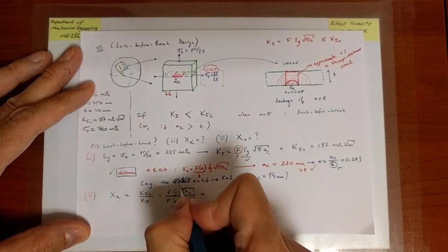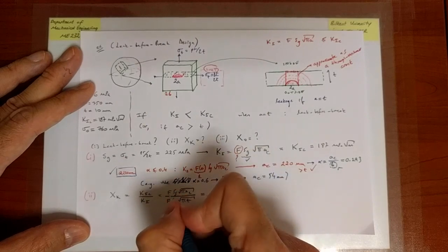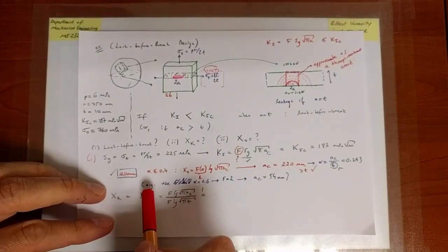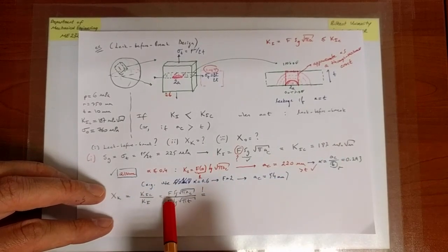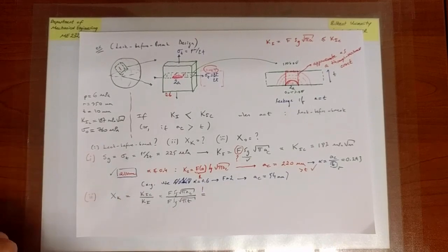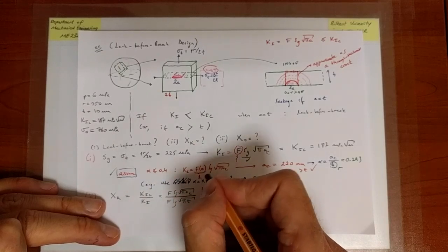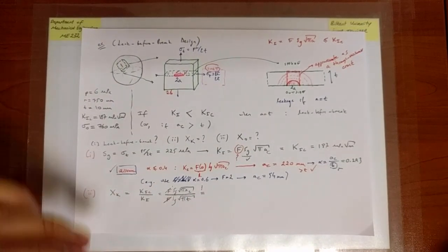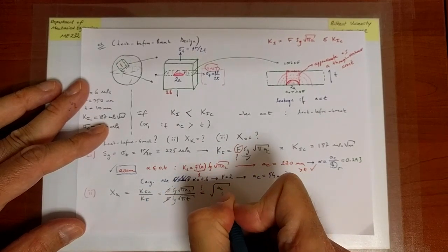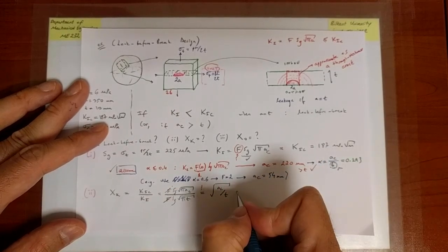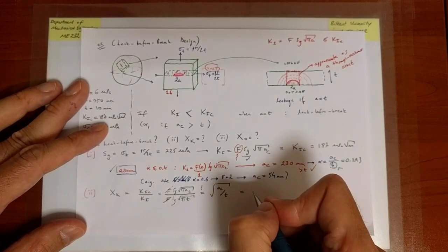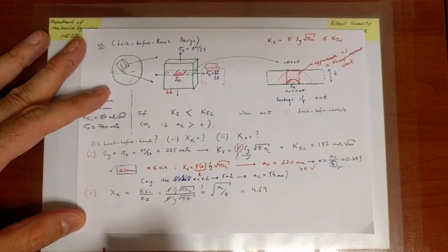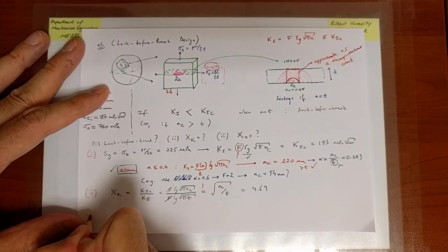Okay? So what I can therefore do is simplify: sigma is the same, root pi cancels, and I'm going to cancel F2. Now here is a caveat. I'm doing another level of simplification here, which you don't need to do if you plug K1C equals 187 directly and take the value of F corresponding to the value of T. But I can do that simplification over here. I'm going to assume that this F is negligible. It's almost 1. And this F certainly is negligible because T is very small. Therefore, these F's are not there. And therefore, the ratio is simply AC over T. I know the value of AC to within my approximation. I know the value of T, that's the thickness. The value comes out to be 4.69. Okay, so that's the safety factor on the stress intensity factor against fracture. So it seems that we are quite safe against fracture, again, to within our crude approximations.